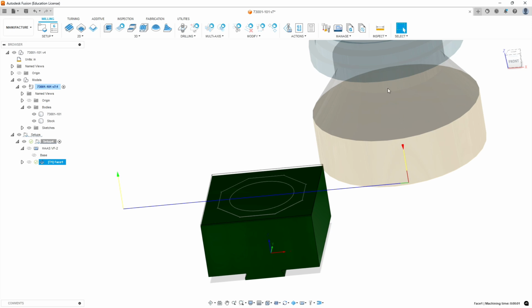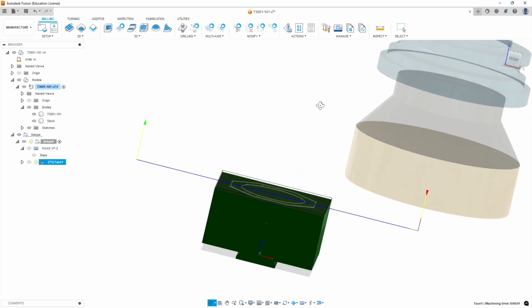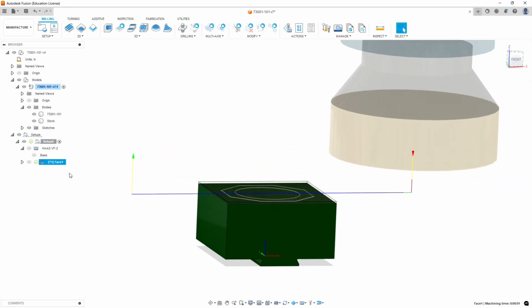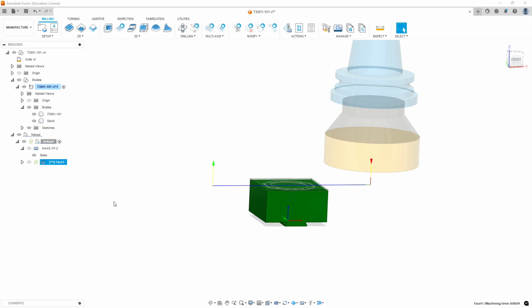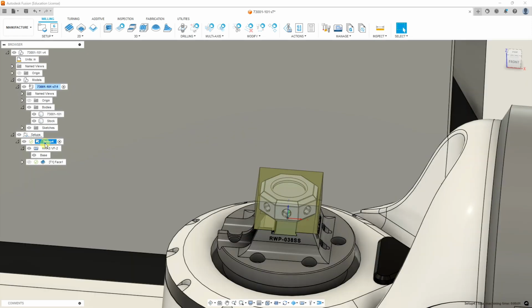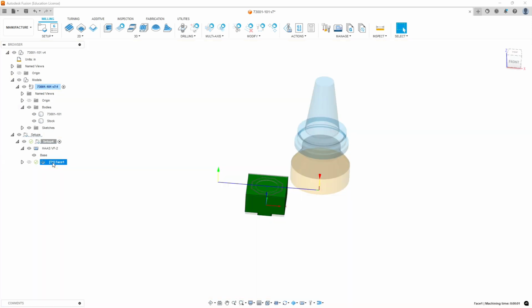All right, so now we're going to come down and over to the right and feed to the left and pick up. I'm not so sure I like that because we have this big rotary table over to the right. So let's take a look at where this occurs with the machine in play. And if we look at the machine right now, we have it plunging at the right and going to the left.